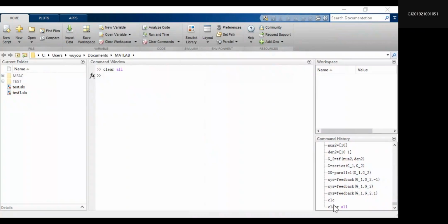Then how to draw the second one? First, duplicate it. So you have two transfer functions here. And then click it, and it shows up a transfer function parameters block, and then you can set up all the parameters you need. And here, it's just the code we're familiar with. It's just separated into some blanks we need to fill in.